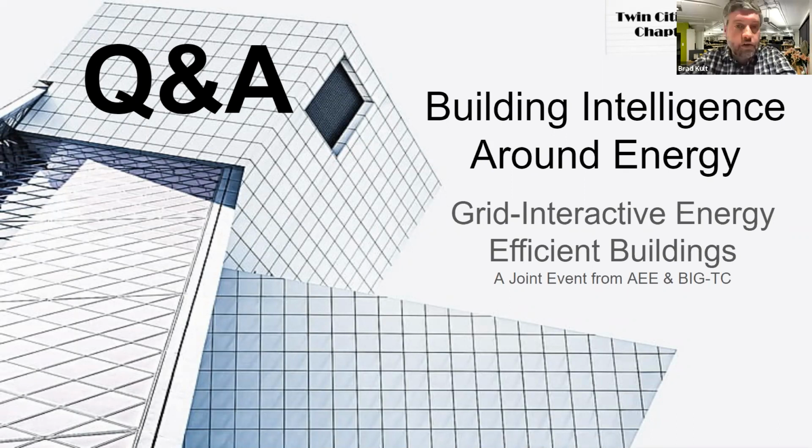Ben, you had mentioned using plate level information along with runtime info to calculate energy use. Is the plate level equal to nameplate level? Yeah, right. So that's the consumption for the equipment, the nameplate level data captured and entered into the system. The example I used was 75F, which has that as a built-in capability. It takes a bit of work to go around and gather that, assuming you can read the nameplates and pull that in. But yes, it's pulling the power, at least the out of the box or new equipment draw levels, off the nameplates.